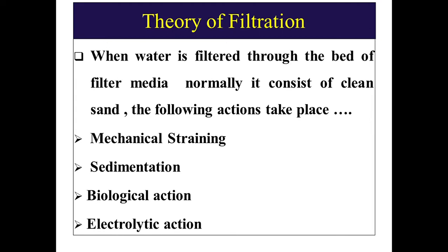What is the theory of filtration? When water is filtered through the bed of the filter media, which normally consists of clean sand, the following actions take place. One is mechanical straining, second is sedimentation, third is biological action, and fourth is electrolytic action. The fourth action is very important for the filtration process.